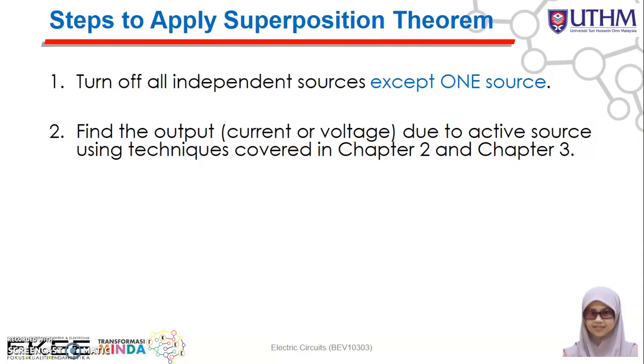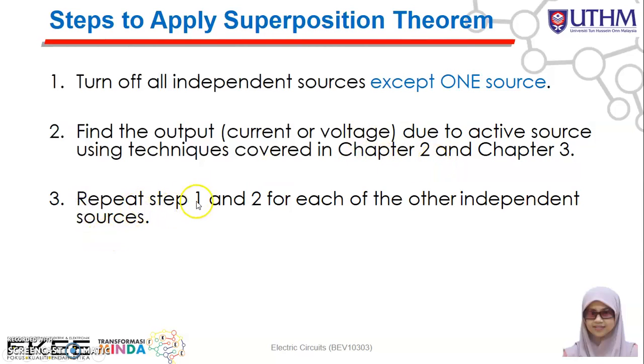Maybe you are going to apply the mesh analysis, Kirchhoff analysis. Okay, so it depends on the type of circuit that you get. All right, and then after that you need to repeat step 1 and step 2 for each of the other independent sources. Let's say you have 2 sources, so you need to do it 2 times. Let's say you have 3 sources, then you need to repeat 3 times.